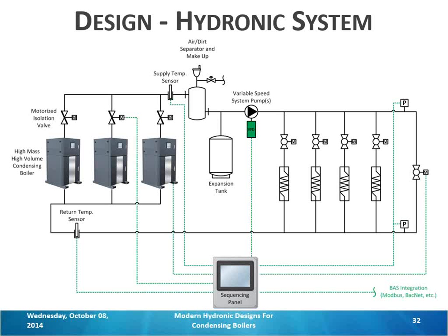And if you're implementing a delta T logic on the pumps, you can also do what's called indoor reset. So already controlling outdoor reset and lowering the set point return water temperature off outdoor temperature. But if we have to slow down our pumps further, we can actually drop that supply temperature a little bit to get the return even lower. Because for whatever reason, the building has less load than what it was designed for. Maybe it's full of people, there's a convention, there's computers, there's the sun shining. For whatever reason, our load dropped. So we don't need as hot of water.